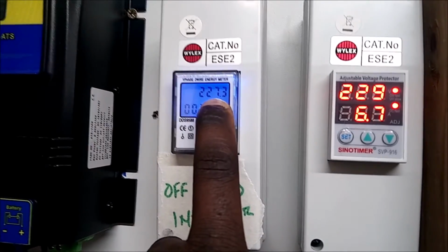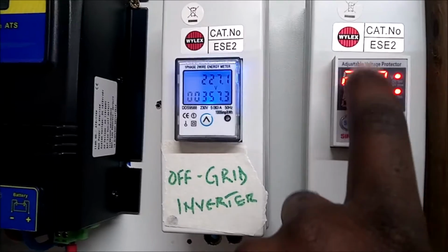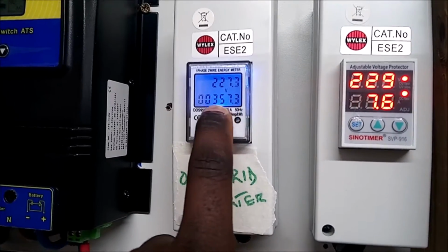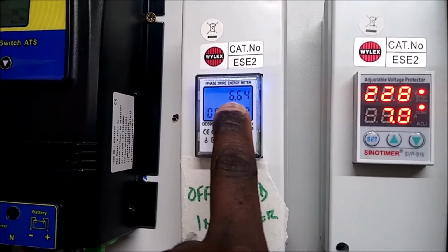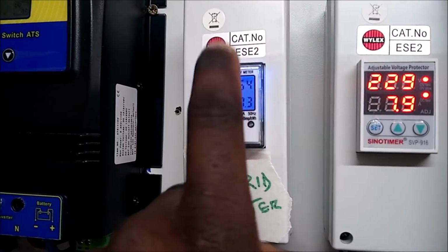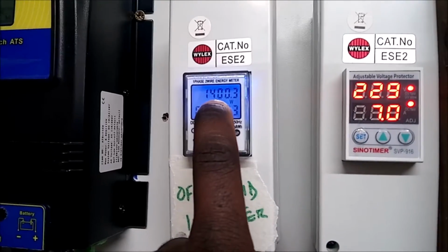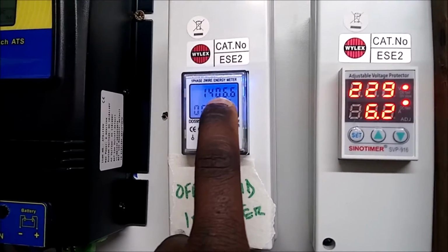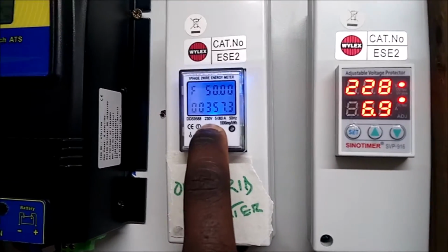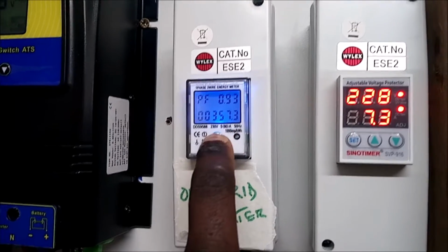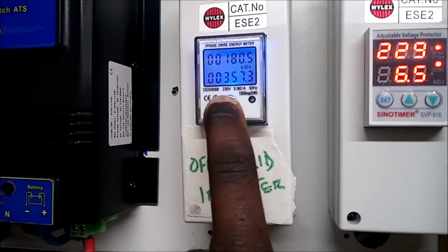Right now, I'm doing 227 volts. You can also compare the data here. This is more in real time, but this is a little bit in delayed mode. And right now, making 6.6 amps. That's what I'm consuming in real time based on the load on this. And based on that, I have 1.4 kilowatt appliance on this right now. That is my frequency, and this is my power factor, which is quite good. That's because I've got a lot of loads on it right now.